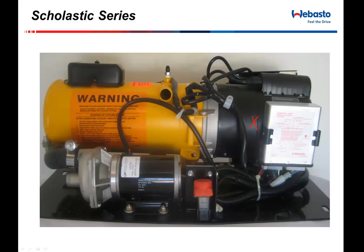There's a flame which will be created through this yellow heat exchanger portion, and that's where the heat is actually being generated and transferred into the coolant system. Water or coolant comes into our water pump, goes through the heater, and comes out this top port.